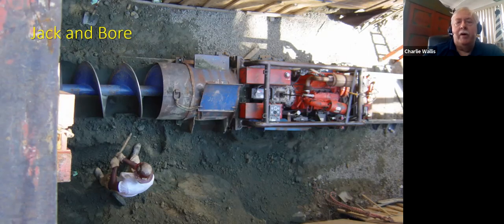Sometimes an existing roadway serves as a dam embankment, and for one reason or another, a new spillway pipe needs to be placed in the dam. And since a lot of roads can't have open cuts because of the traffic that's on it, instead you tunnel underneath of the roadway, and the process is known as jack and boring. And this is a jack and boring machine here.